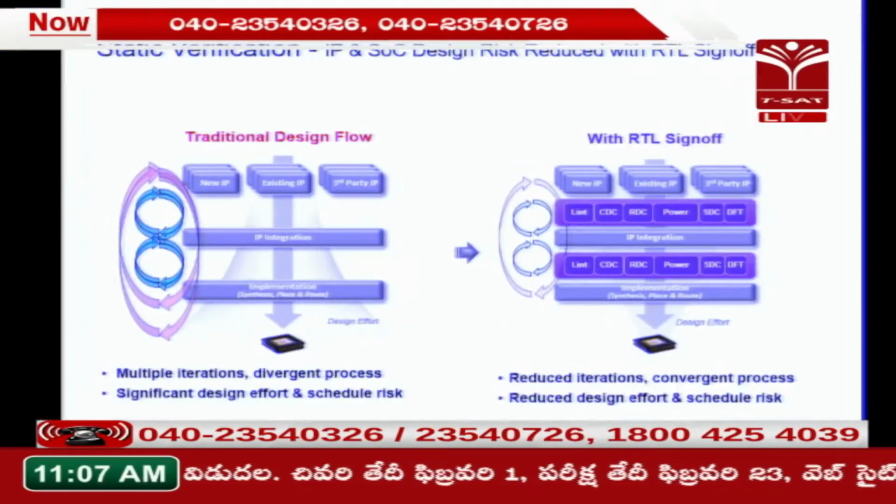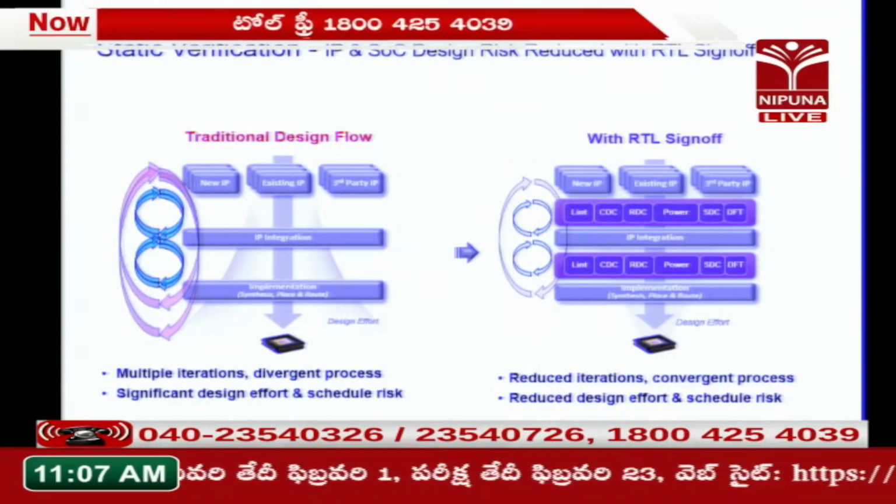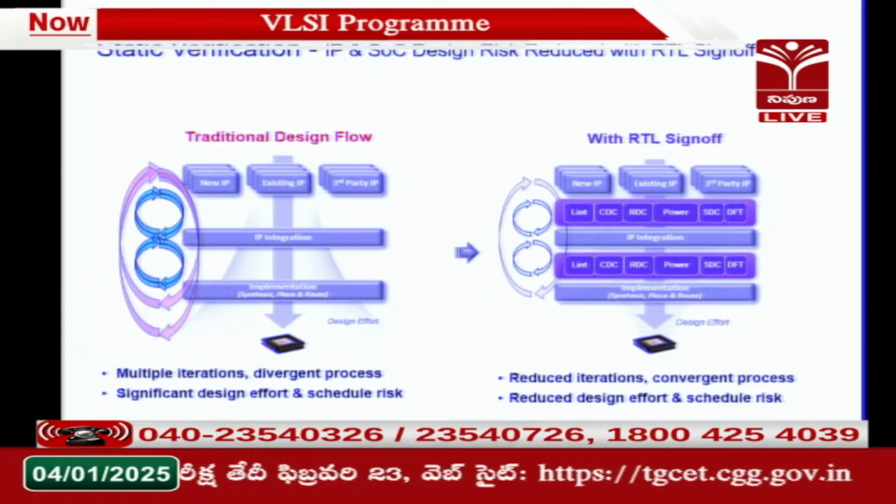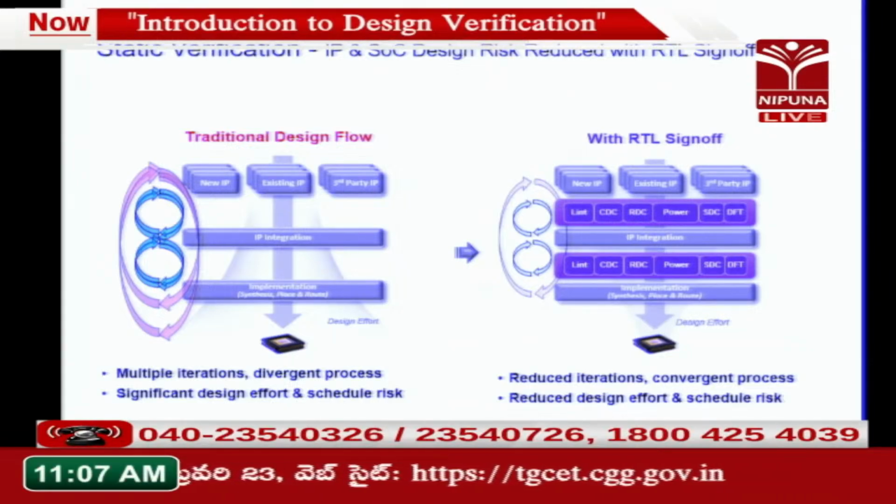In case of static verification, what it provides is various mechanisms to do these construct-based checks as well. So you have lints. Lint means whatever code you are trying to write, it will parse each line of the code, understand the constructs, and say if your code is a good code or not, a clean RTL or not.